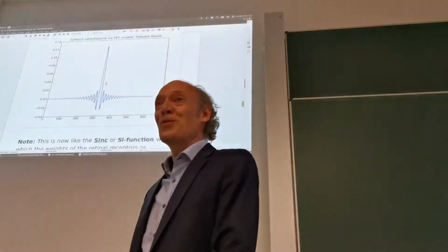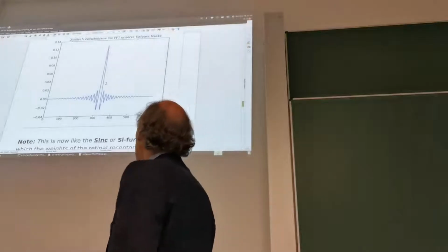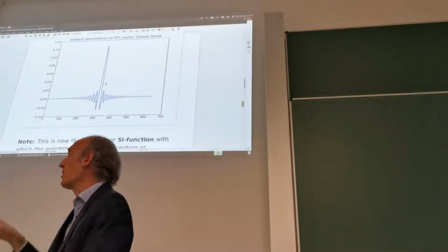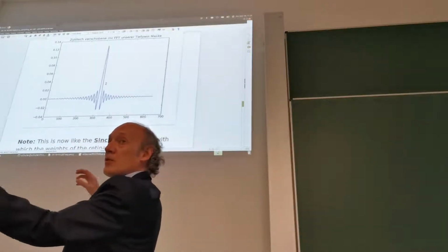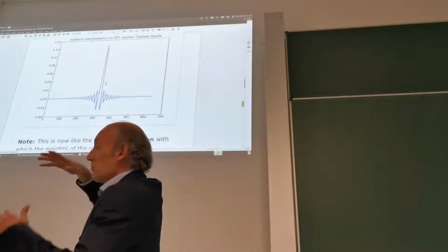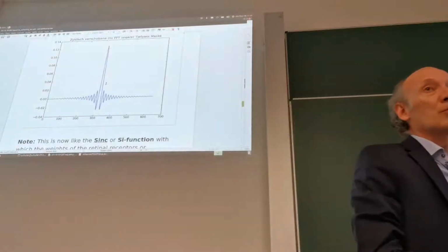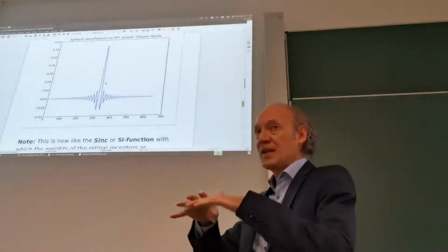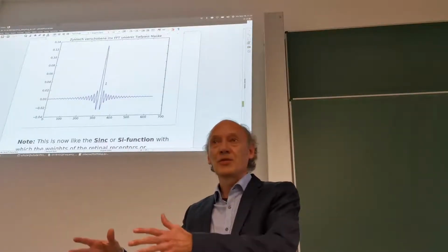You see that it now looks more like a sinc function? Here you can see the middle part, the main lobe of the sinc, and then we have those ripples to both sides, which in theory continue to infinity and slowly decay. This is also what you would expect, because the FFT of a rectangular function, which is basically our mask, is a sinc function. Right?